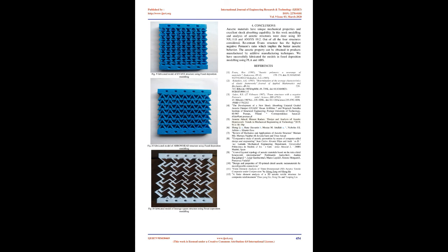Fabrication. The materials generally used for preparing auxetic structures are polylactic acid, acrylonitrile butadiene styrene, nylon, titanium, nickel, steels and AM materials. Generally auxetic structures are difficult to manufacture; even so, the suitable technique for manufacturing auxetics is additive manufacturing. In this work we fabricated the 3 models of our structures using PLA and ABS materials by a 3D printing machine using FDM, as shown in Fig 9 and 10.